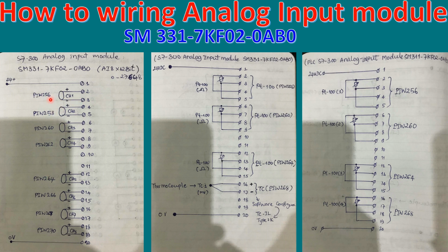And the address will start from PIW 256, so there are 8 channels in total. It will start from PIW 256, 258, 260, 262, 264, 266, 268, and the last one is 270. Okay, so this is option 1 if we would like to use current or volt.